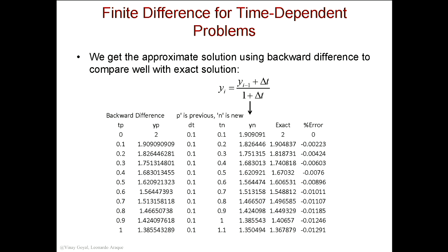Likewise, you can have problems where things are happening in a fraction of a second, like an impact dynamic event or a hail impacting a composite. I want to know how the composite structure responds, which is a good application for aircraft structures, right? In that application, I want to know what kind of damage the hail is going to do to the composite. There, I'll probably want to reduce the time step to scales even less than 0.1 seconds, because everything's happening maybe in microseconds, right?